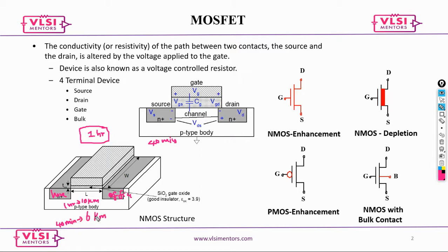Now what is it that you are trying to do here? What do you understand from this? Now you reduce the distance. Basically, the length reduces, and your delay, the amount of time it takes for the charging, gets reduced because the charges have to travel less distance only. Okay, so that is what we always consider, like, L. When L reduces, your delay, usually the charging time, reduces.